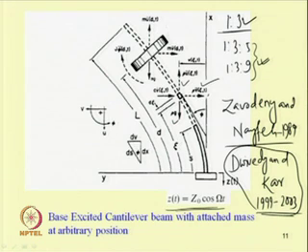So, if the mass is taken into account, so this is the end mass. So, end mass also will have this m u double dot, m v double dot. So, this is the position at a distance d from this base. So, this is the deformed length d, this is undeformed length L, L is the total length of the beam, considering inextensibility condition.